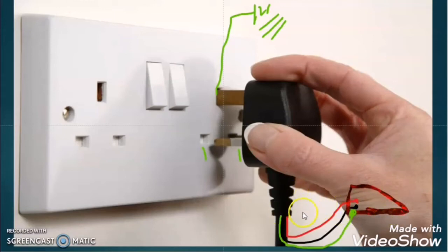So what is the benefit here? Before the power supply reaches the load, the body of the load gets earthed, and then the power supply reaches the load. Let us reverse this scenario in order to better understand this concept. Let us assume that the earthing pin is shorter in length compared to the phase pin and neutral pin.